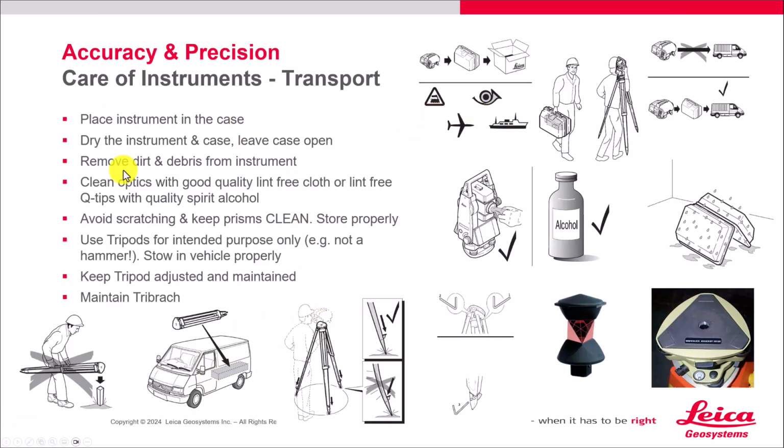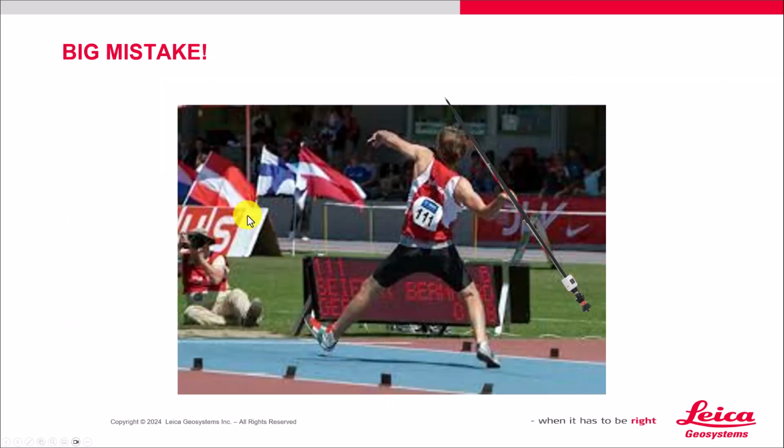Well, I won't read all these to you, but you should know most of the care you should take. You keep them in a case, avoid scratching the prisms, maintain a good tribrach. Use tripods for the intended purpose. So you've got a lot of examples here. Don't use a tool for the wrong reason. Don't use your tripod as a hammer. Take care of this equipment. It costs a lot of money, and it can handle some abuse, but not a lot.